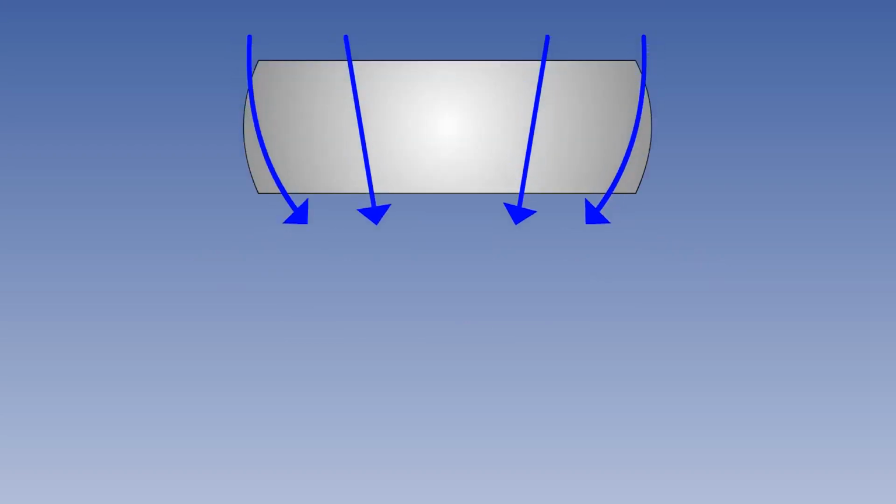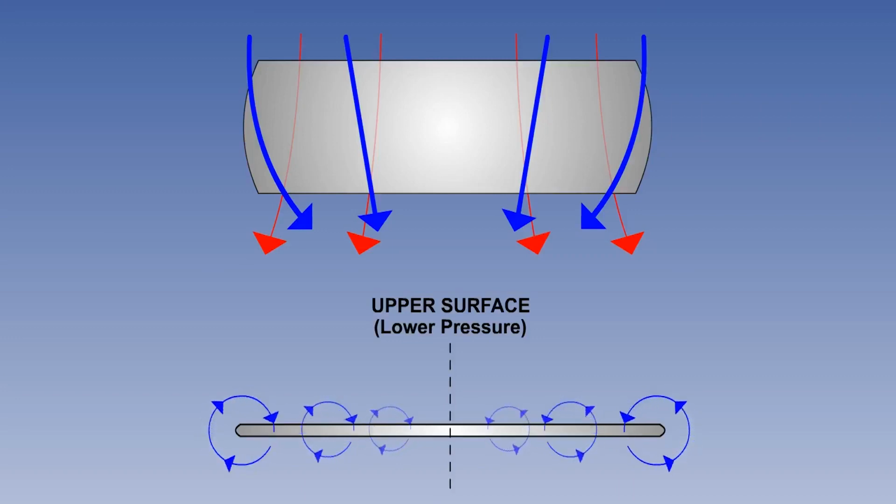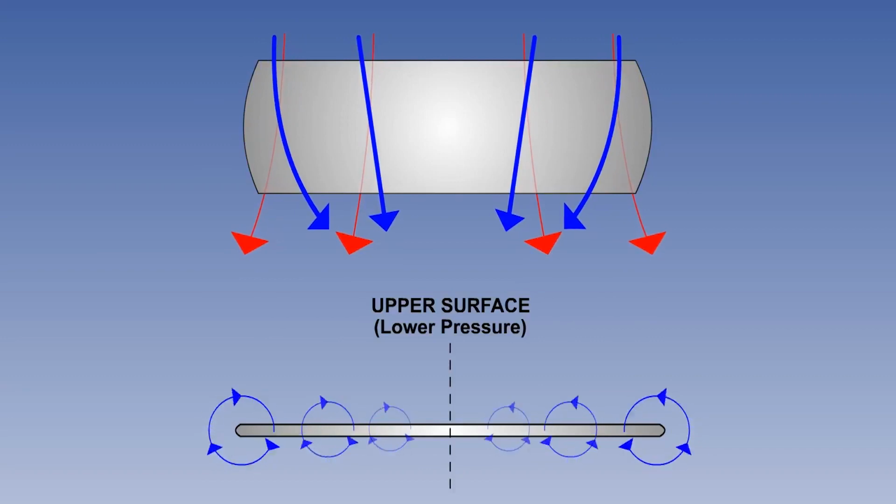The airflow over the top surface of a wing is at a lower pressure than that below the wing. The two flows are modified by this pressure differential, which creates a spanwise element towards the root on the top surface and towards the tips on the lower surfaces, and these flows interact at the trailing edge and wingtips. In the conventional view of the aircraft from the rear, the vortices produced by this interaction rotate clockwise at the left wingtip and anti-clockwise at the right wingtip. At lower IASs, and therefore higher angles of attack, the decreased chordwise vector and increased spanwise vector, due to the greater pressure differential, will increase the resultant spanwise flow, making the vortices stronger.